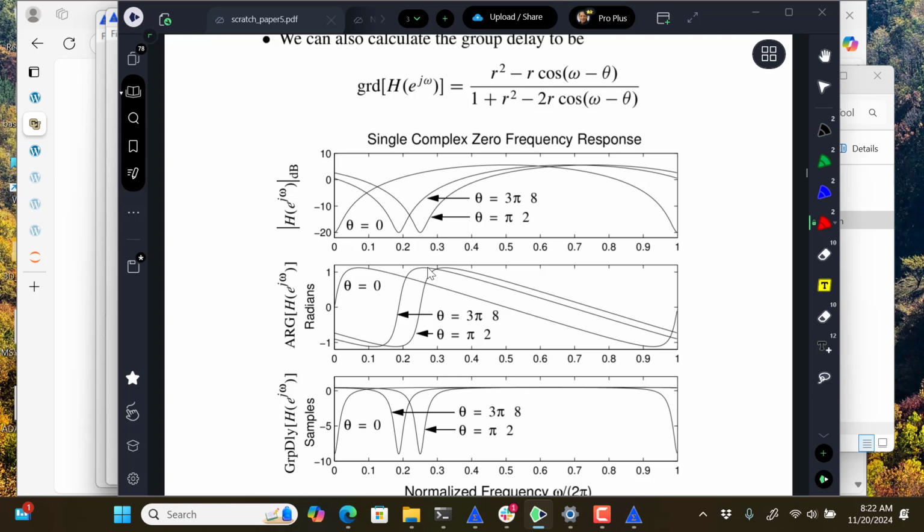And this just carries it down to show what the phase looks like. You have a phase inflection when you go through that point where it gets close to the 0, and then the group delay, being the minus derivative of the phase, has a negative bump on it. It's approximately 0, and then it jumps down and comes back up again.